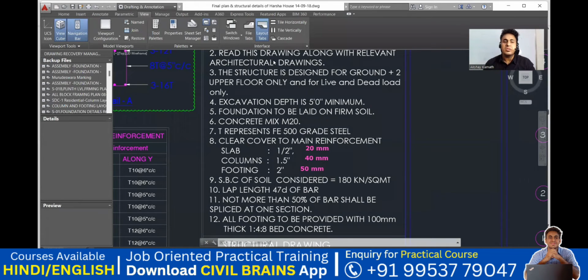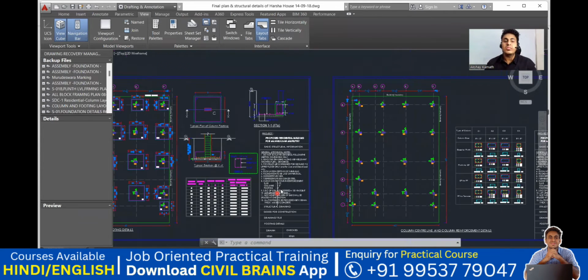Next is the safe bearing capacity of the soil, which is 180 kilonewton per square meter. And the lap length is 47 times the diameter of a bar. And the rest of the things are okay. For the footing, wherever you're putting the PCC, it has to be 100 thickness of PCC, that is plain cement concrete, and the ratio is 1 is to 4 is to 8. So this is the basic explanation they try to give.